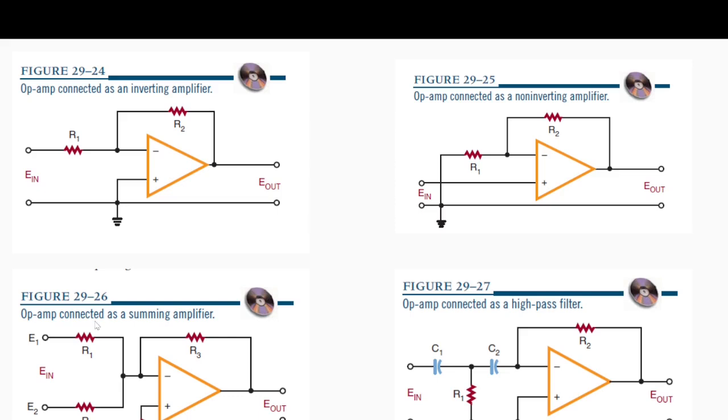This is also called a summing amplifier, and we will discuss its mathematical equation further. Whenever you see multiple resistors connected at the inverting or the non-inverting inputs using an op-amp, most likely that is going to be a summing amplifier. It sums up the voltages and amplifies them, and the feedback resistor is the very important reason behind that amplification.